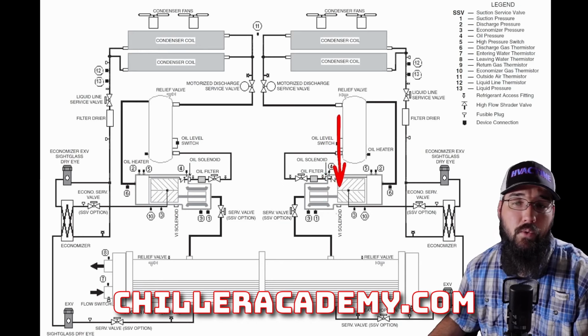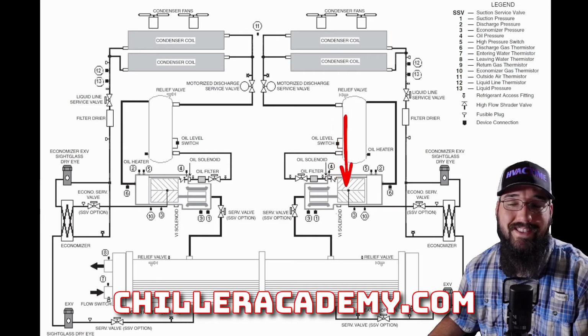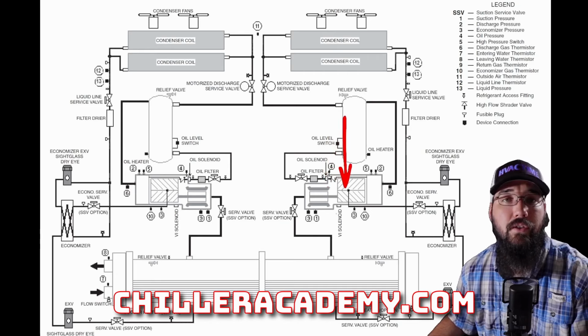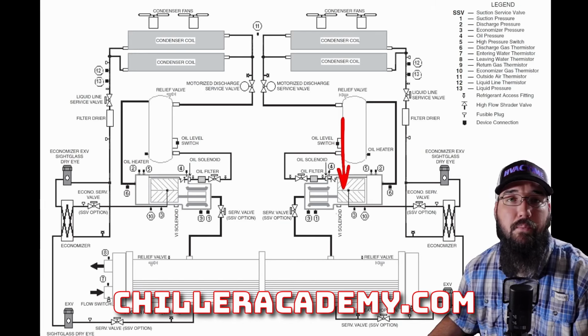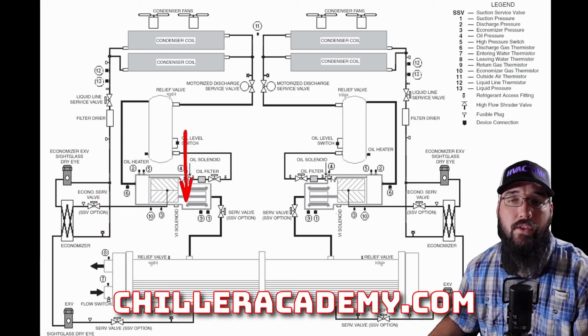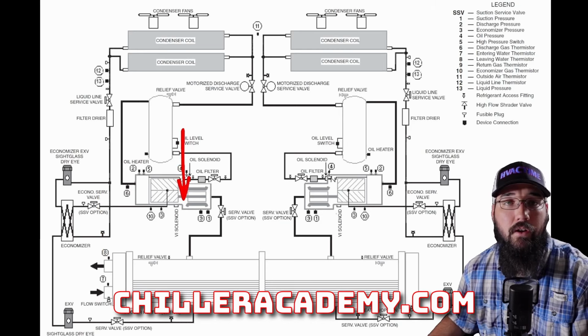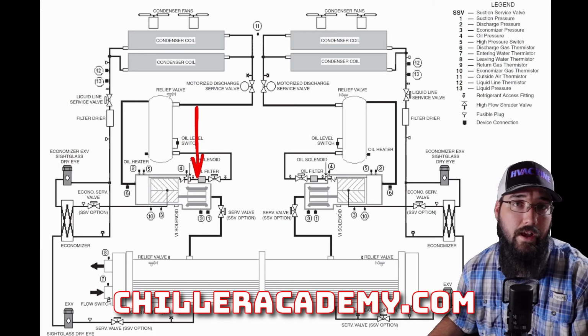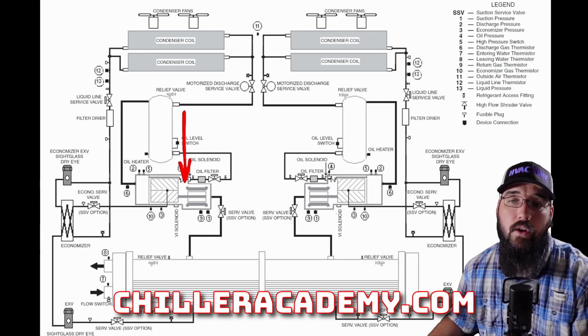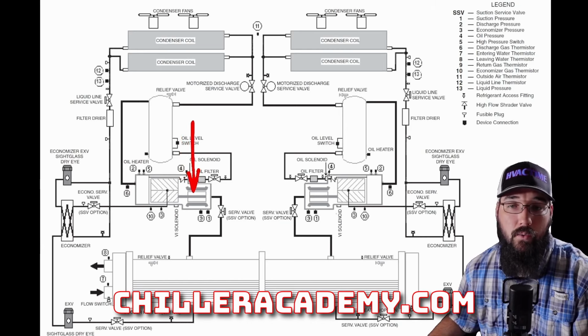And when we get to the point where the system has registered that the compressor has maxed out, it is ramped as far as it's capable of going and we can't put any more load on it, but we're still not making our leaving water set point, then we will decide to bring on one of the lag compressors. So let's say circuit 1 was our lag 1, and we could have a lag 2 or lag 3 depending on how many compressors. Let's say lag 1 was compressor 1. Lag 1 would get started, and it's going to start to ramp up.